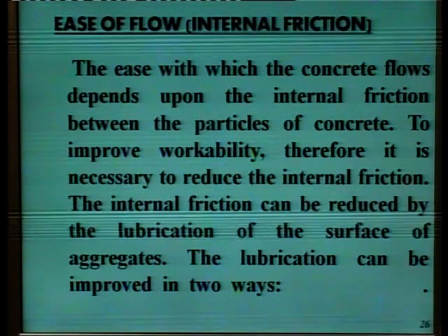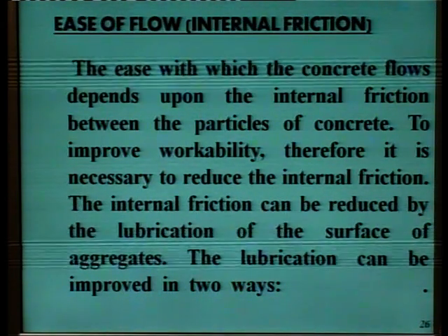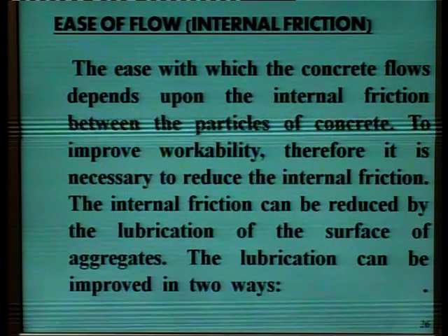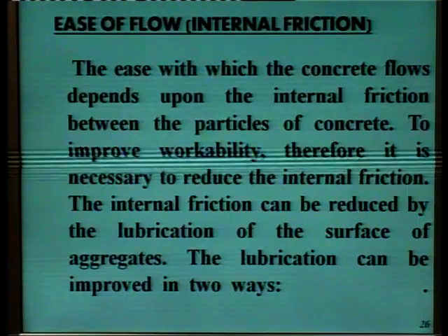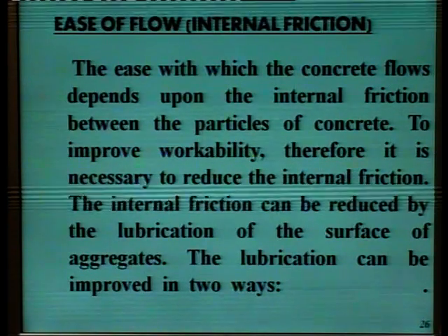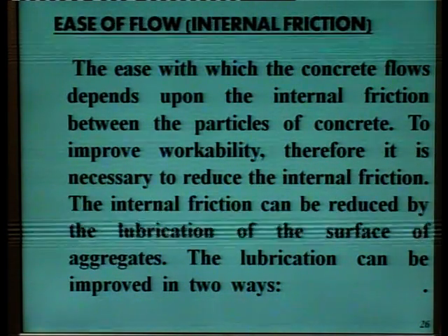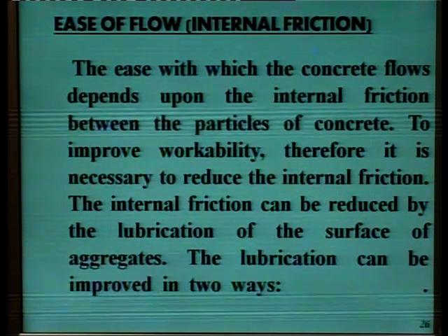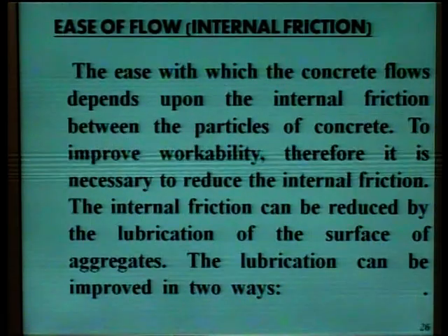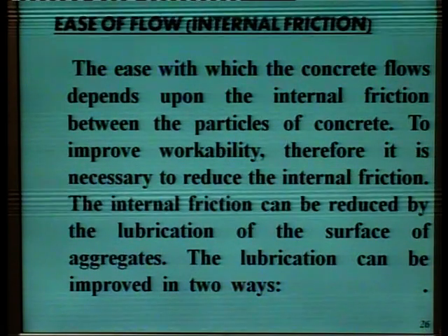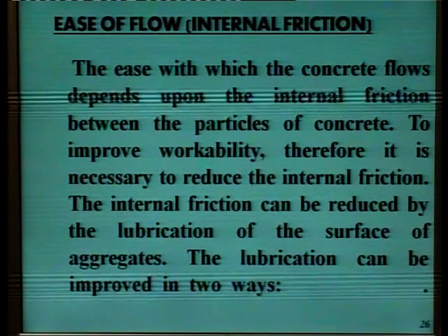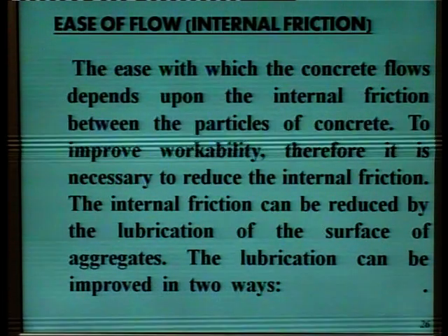To improve workability, therefore, it is necessary to reduce the internal friction. The internal friction can be reduced by the lubrication of the surface of aggregates.